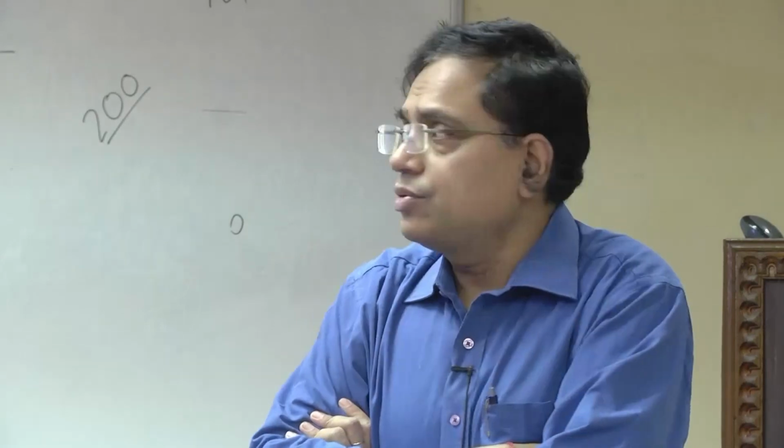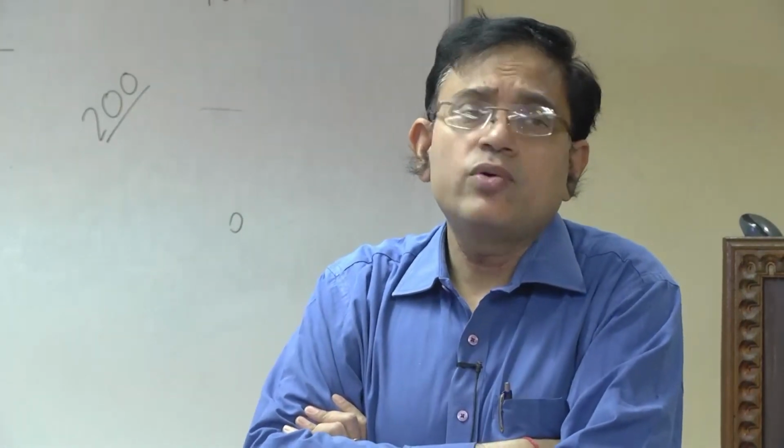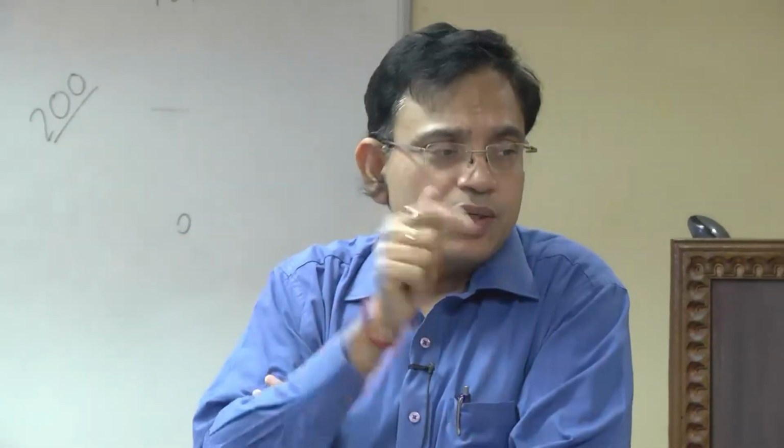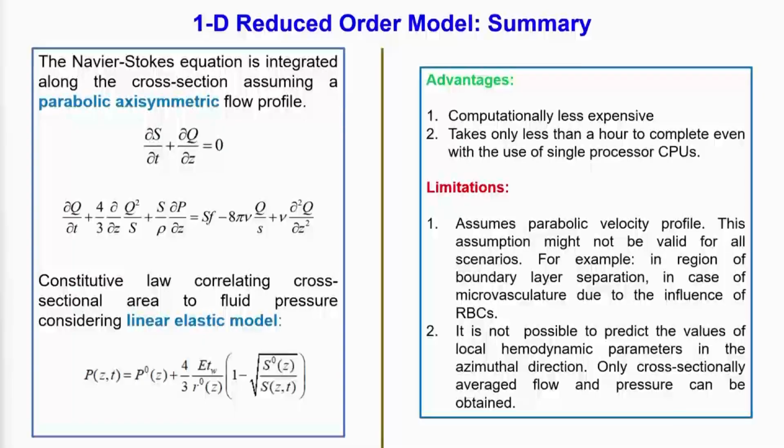We applied the equation of equilibrium for the solid part of the domain, integrated it and got the displacement, and that displacement we related to the pressure. From there we got the expression, and displacement will be a function of the modulus of elasticity, etc. A similar thing applied here for a linear elastic fluid gives exactly the same as that one, and the square root of S is there because we are talking about radius, and radius is proportional to the square root of the cross-sectional area.